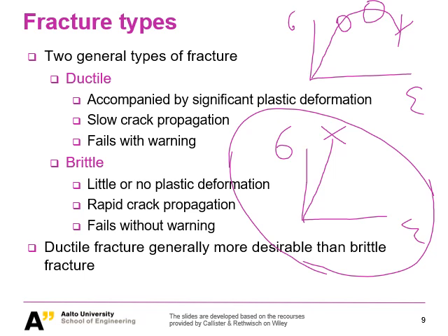As human beings, we have accumulated a lot of experience, a lot of failures in terms of brittle fracture, to improve and shape our engineering practice in aerospace, in bridges, and in automotive, all these cases. That's why in design, as one of the prevention rules, we always consider ductile fracture generally more desirable than brittle fracture.